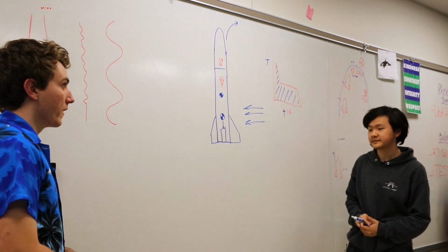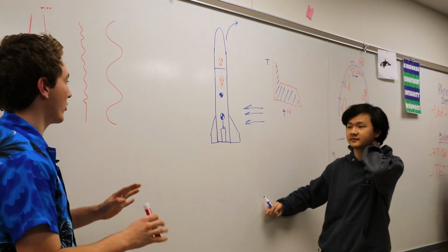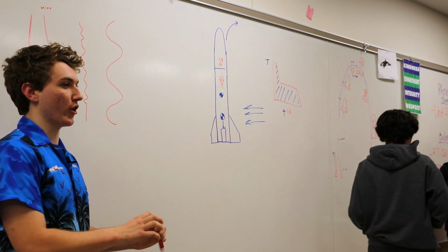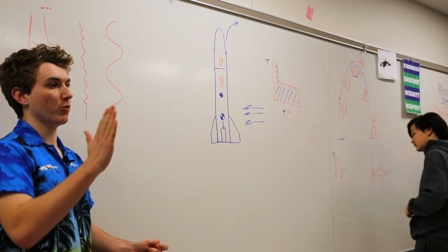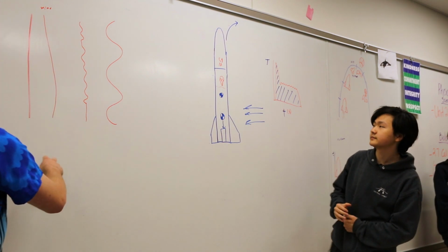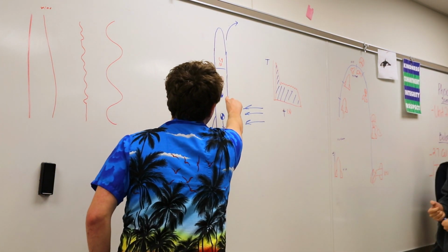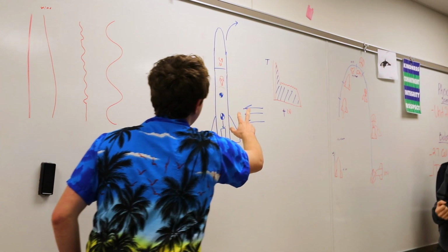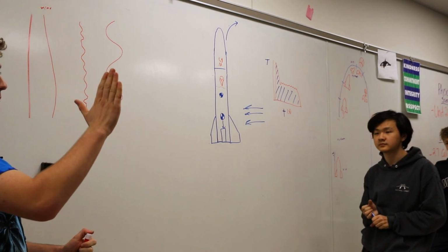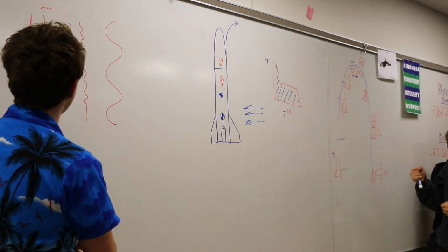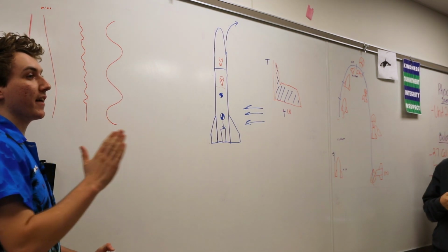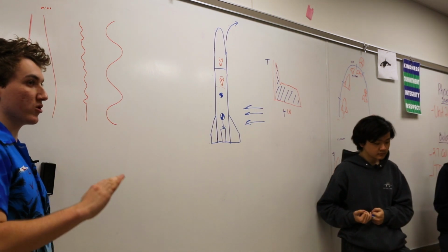This is measured in stability. There's a more technical way to do it, but I'm just going to use the term stability. It's not that stability is good. Stability is just a measure of how much the rocket will react to sideways forces, from wind more or less. If you have a rocket with a stability of, I believe, 0.5, it'll go straight in the direction wherever it started. It won't correct. Once you get to about 1, it'll correct a little bit. And once you get above 3, it's going to correct a lot. So it's not that more stability is better, it's more stability, more correction.